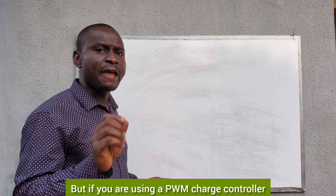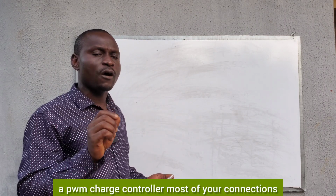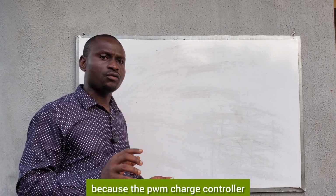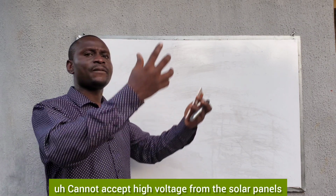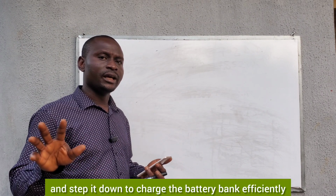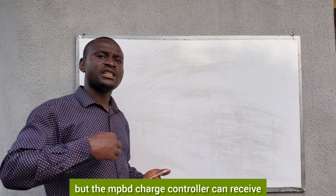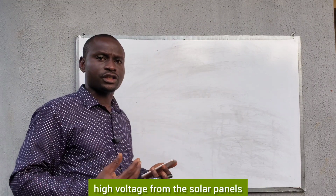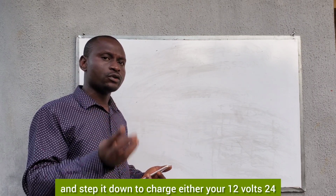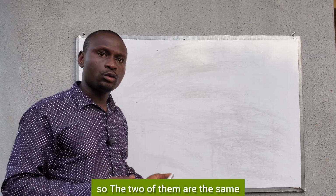But if you are using a PWM charge controller, most of your connections will be in parallel, because the PWM charge controller cannot accept high voltage from the solar panels and step it down to charge the battery bank efficiently. There will be a lot of losses. But the MPPT charge controller can receive high voltage from the solar panels and step it down to charge either your 12 volt, 24 or 48 volt battery bank. So the two of them are the same.